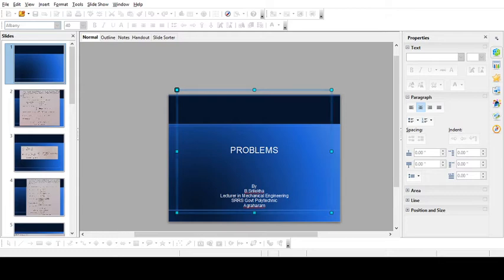So we'll substitute 2.004 into 10 to the power of 5 instead of E, and we are going to find C, and instead of 1 by m we are substituting 0.2967. So shear modulus C is equal to 2.004 into 10 to the power of 5 by 2.5934.